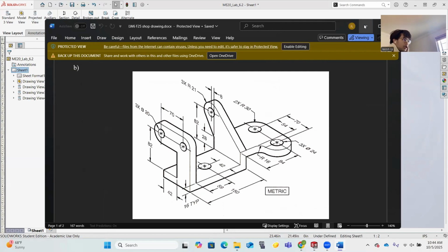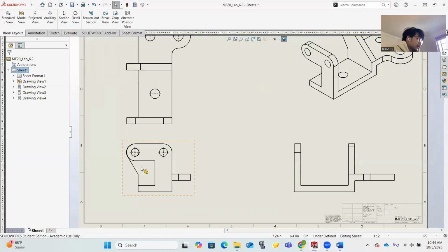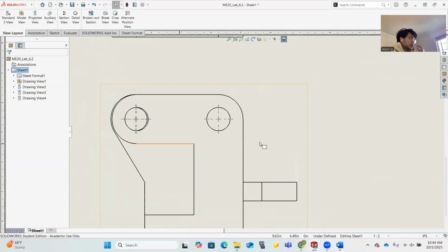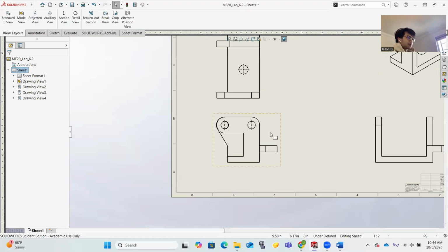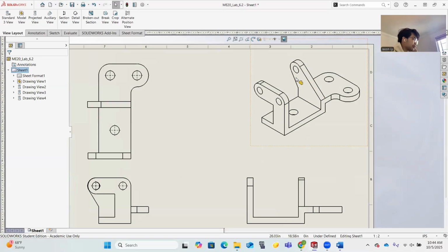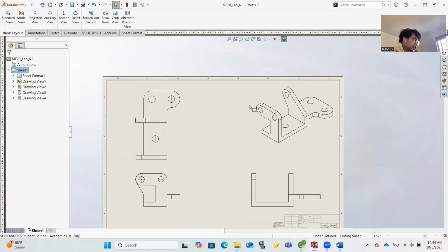So if we look at our drawing right now, currently, this face, we could dimension this perfectly, right? But the one behind it, it might be hard to dimension, and we can't really dimension it, right? And from our three standard faces, we can't do that besides ISO view, but we never want to dimension in ISO view, right? This is strictly off limits. This is only to show the engineer what the part should look like if they can't really imagine it.